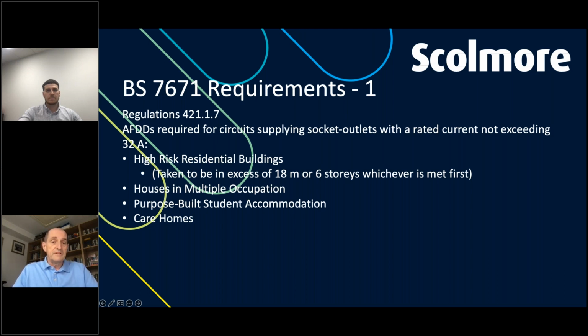The UK's position is in one sense different to that which occurs in the harmonised document that came down, but it is, I think, internally consistent. We actually recognise that AFDDs have a use. They're very useful for final circuits, and they're very useful in those areas where you've got increased risk.